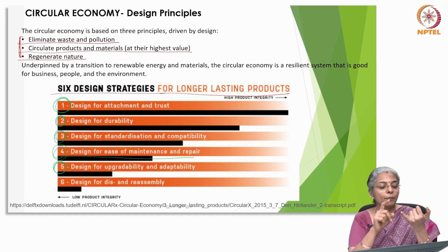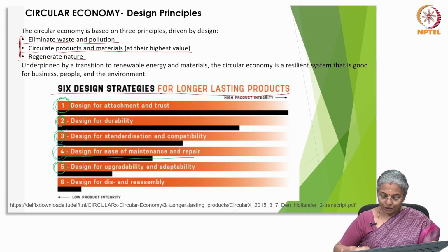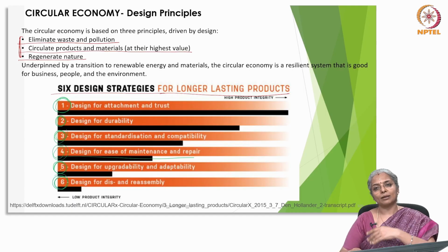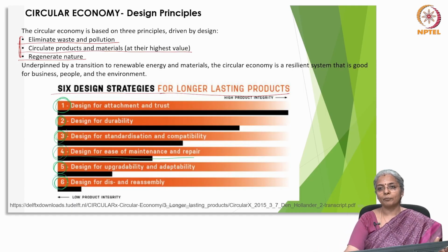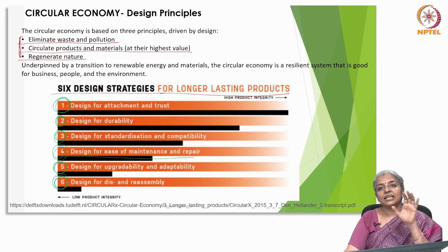When I say design the rope in terms of its texture, I mean it should not be too rough. See, if we are going to use it for packaging or skipping, it should not cut the hands when we use it. So, it should be smooth, it should be made of durable material, it should have enough strength to handle multiple tasks. And then we should also be able to design for disassembly and reassembly, which we will look at in greater detail, because by doing this we ensure that the product part can be spared and reassembled easily.